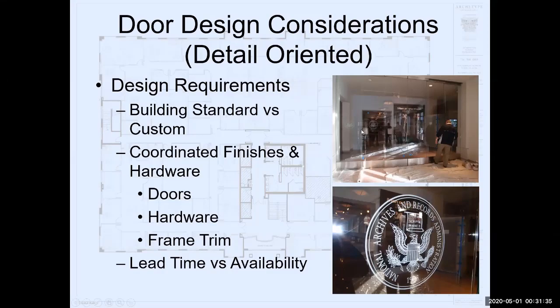So we're at the meeting, looking at them. We had to cut the floor to put in a track here. This is a terrazzo floor, so we had to do all this work at night. My senior architect, Bob, was there at 2 o'clock in the morning watching them cut this floor in, and then we had to do structural work overhead to stabilize the doors because they're very, very heavy.